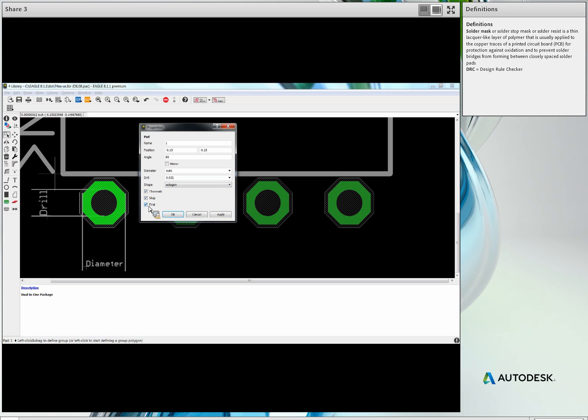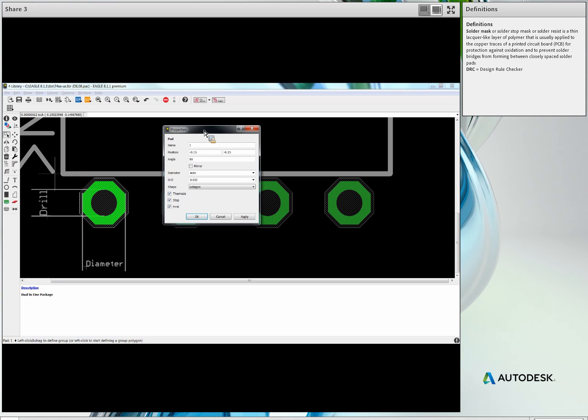First, first it just means that you're identifying that as the pad number 1 pad for this particular component, which is going to take certain effect on the board layout later on. Okay, you don't have to do this. It's just quite convenient if you do. That way you could create some sort of an identifier to see which is pad number 1. Now, stop. The stop, this is an important one. I could have pads not have a stop.